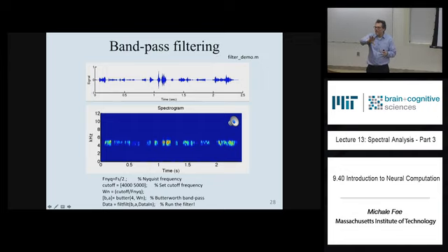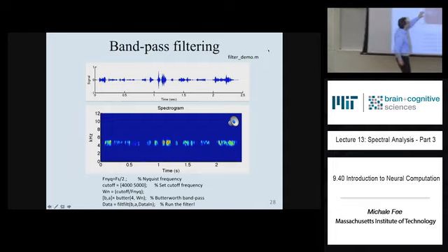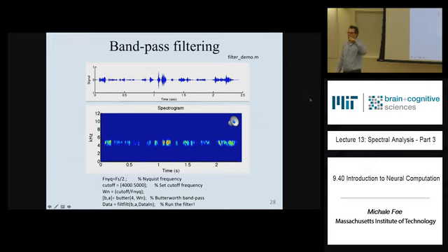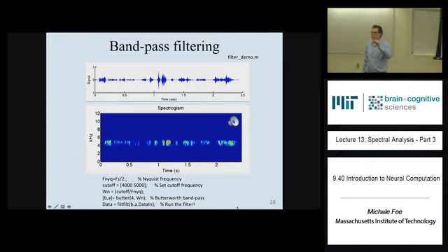You could make what's called a band stop filter, where you suppress frequencies within a particular band. Put that band stop filter at 60 hertz. The problem is it's very hard to make very narrow bandstop filters. So, we learned this in the last lecture, how would you get rid of a particular signal?